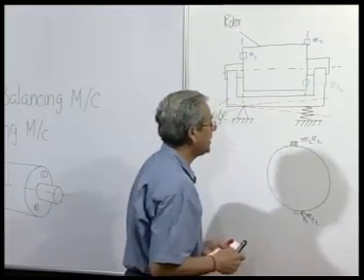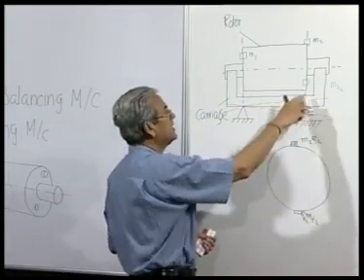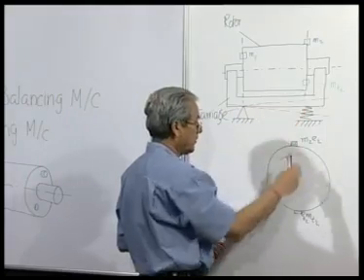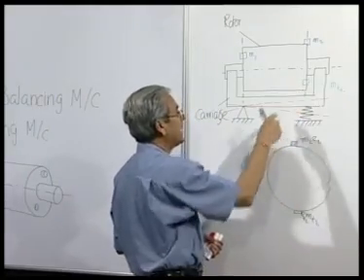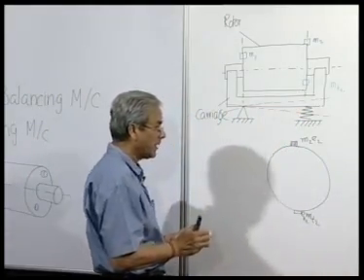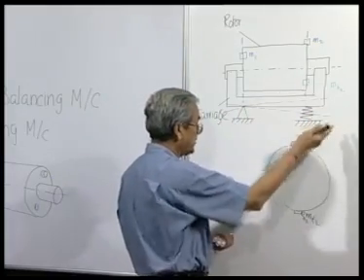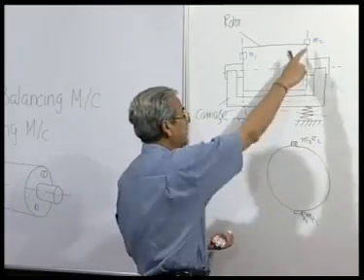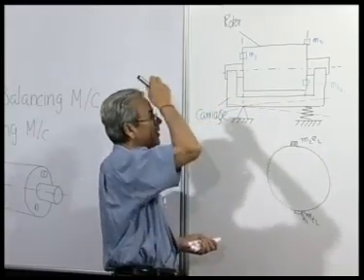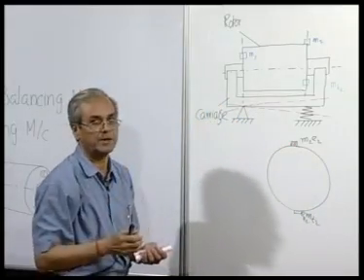So, what we have done, we have completely neutralized the effect of m 2 by putting a suitable balancing mass which has been adjusted to become the balancing mass. The original trial mass has been converted, so that this effect of m 2 in creating unbalance is neutralized.